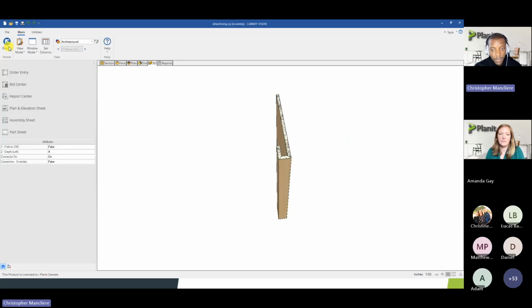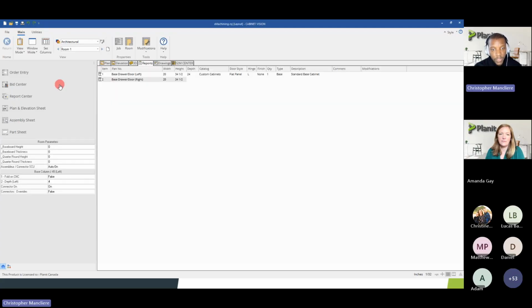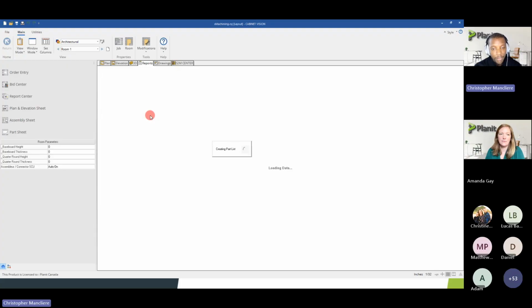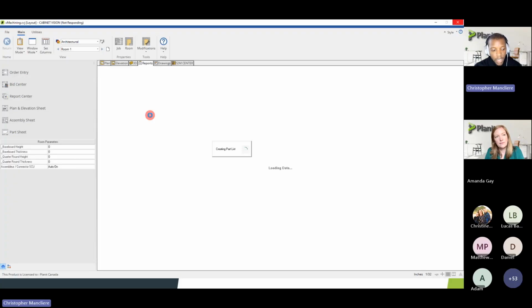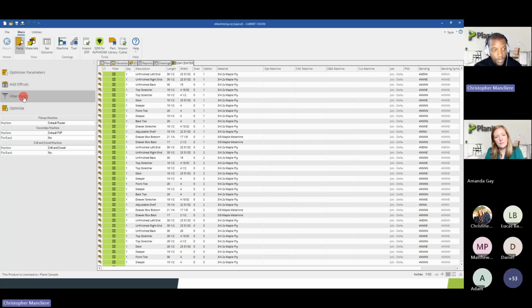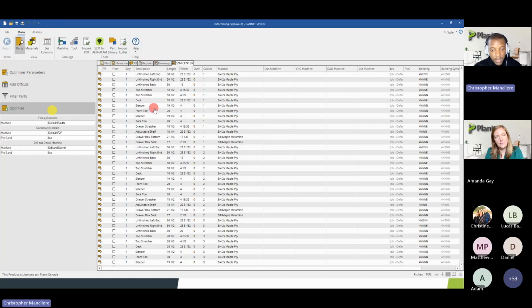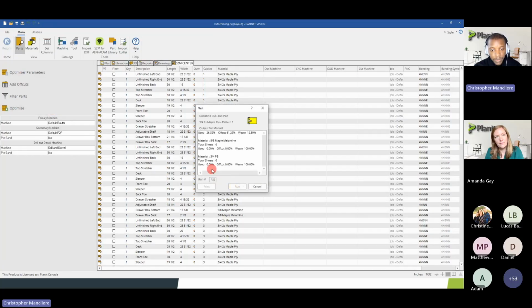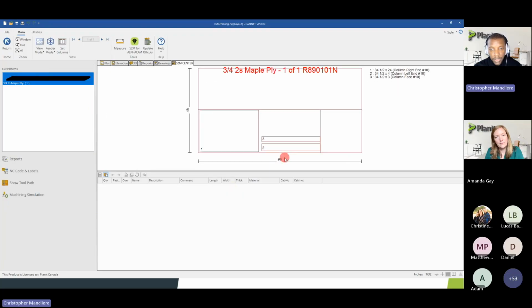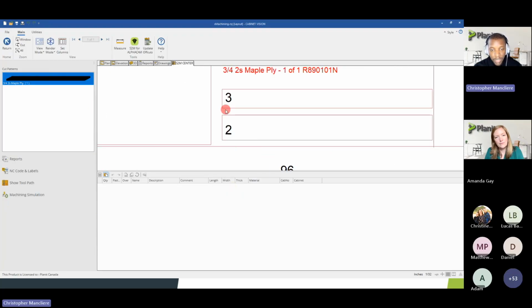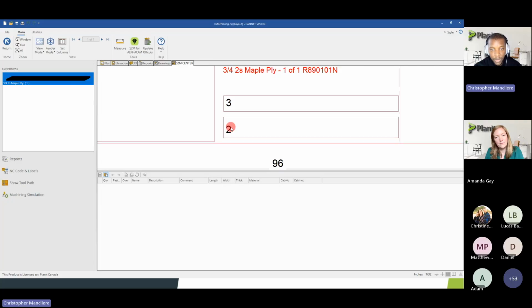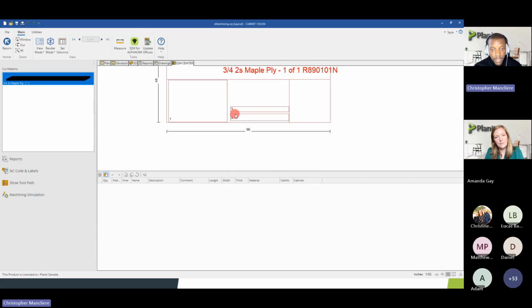So if I do it this way and show you, because I set my V-bit to have a 3/4 nest gap padding, it should automatically increase the space between those parts on my CNC. So we'll test it right away. I'll filter and I'll find my column, and let's nest the column, run. And as you can see here, this is not my typical. Usually I should have about 3/8, but here CV did increase the space for those parts on the CNC.